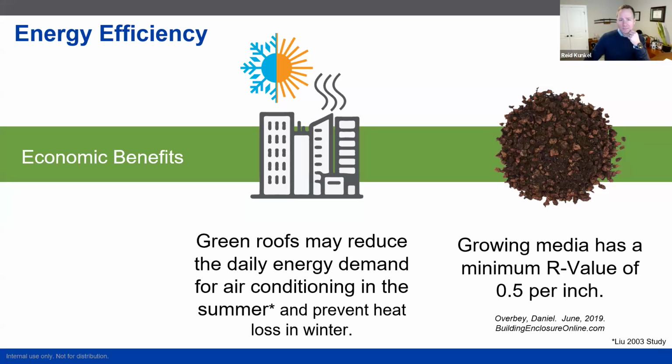And then when it comes time to re-roof, how much more complicated does it get when you have to remove green roofing components and replace them during the re-roofing process? Yeah, it definitely adds another layer of complexity. We have to think about point loads, where we might be able to store those materials while we're servicing another area of the roof.